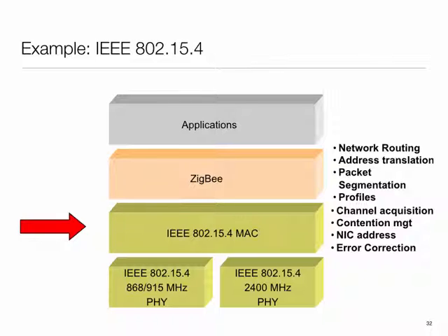It provides a physical layer. I've listed two of them, and there's a more recent third one also, which uses a newer type of radio, ultra wideband. They have a common MAC protocol, and on top of it there's something called Zigbee, which is a set of routing protocols. In parallel to this, the Internet Engineering Task Force has defined something called IPv6 LoWPAN. It's basically the TCP/IP stack which sits on top of this. So there's a whole rich ecosystem out here, and these devices can be on the internet. At the same time, this MAC protocol was designed for low power operation.